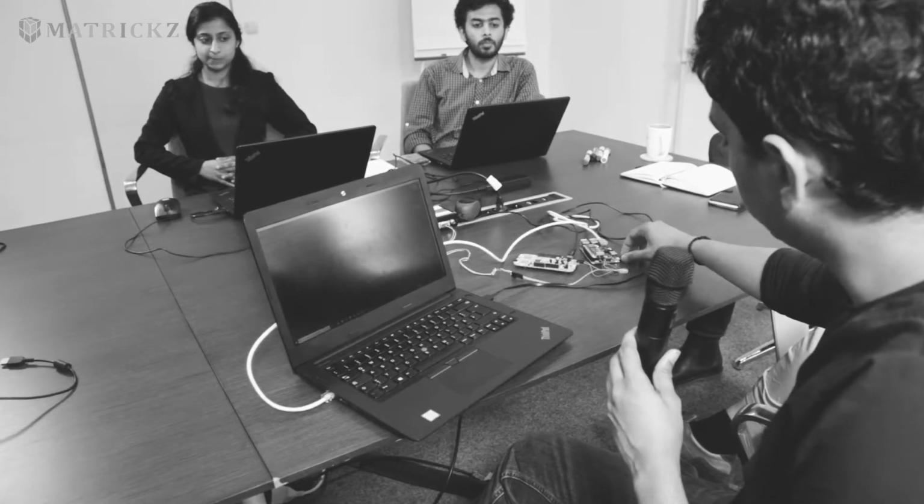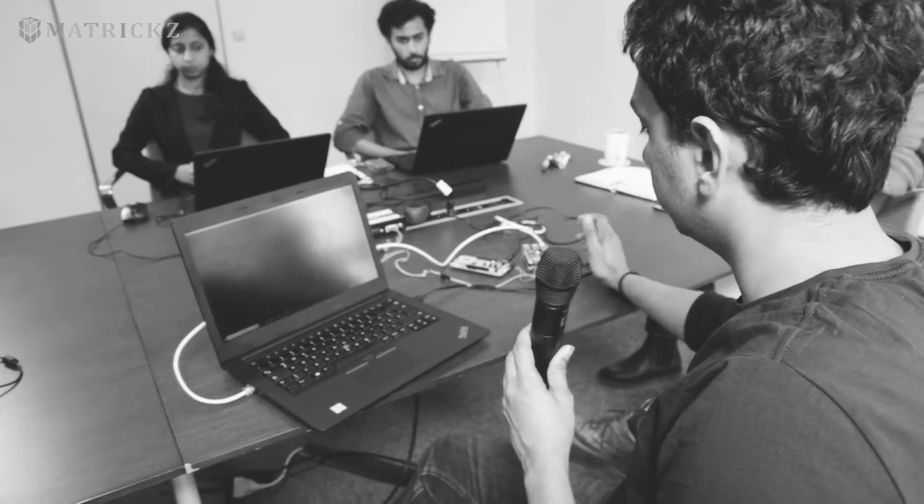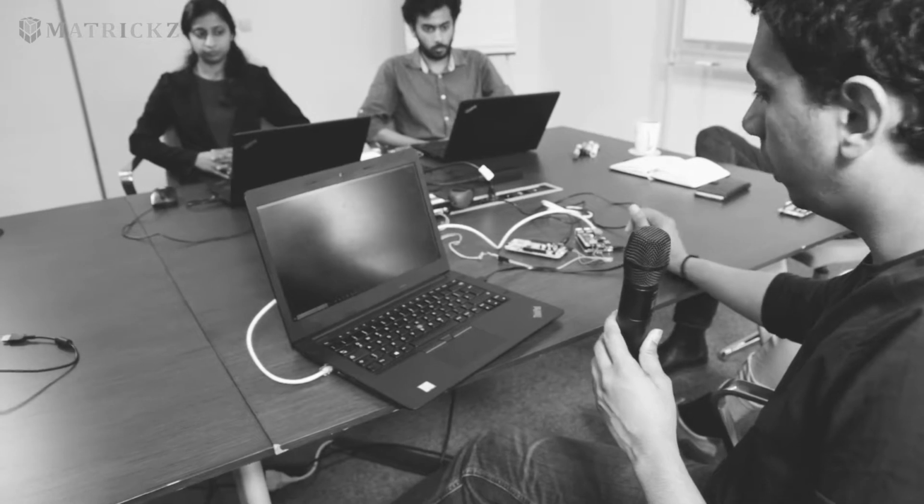So to talk a bit more about the Raspberry Pi, we have used a WaveShare CAN hat to enable CAN communication on the Raspberry Pi, which does not have it by default. It's just a plug and play device which you can buy online and plug in, and we're good to go. It interfaces the SPI interface of the Raspberry Pi with the CAN interface, and you just need to connect it to the CAN. Now we have enabled an SSH connection from our PC on the Raspberry Pi.